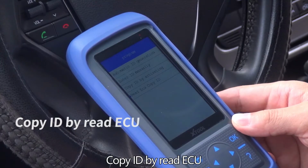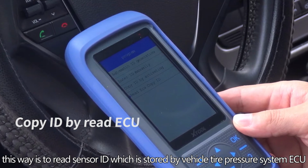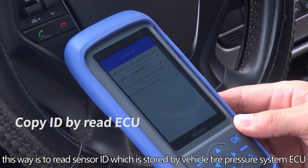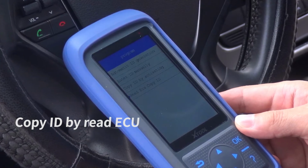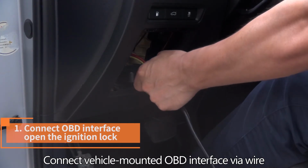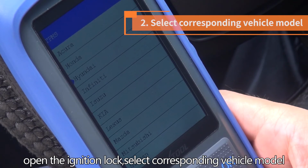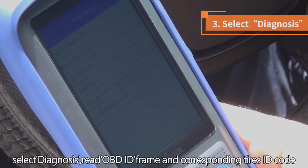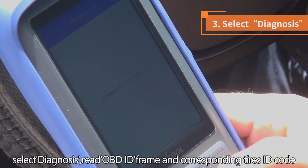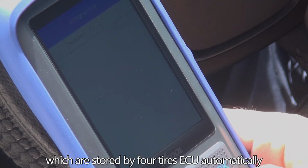Copy ID by Read ECU. This way is to read the sensor ID which is stored by the vehicle tire pressure system ECU and program the ID in the TS100 sensor. Connect the vehicle's OBD interface via wire. Open the ignition lock. Select the corresponding vehicle model. Select Diagnosis, and read the OBD ID frame and the corresponding tire ID codes which are stored by the 4 tires' ECU automatically.